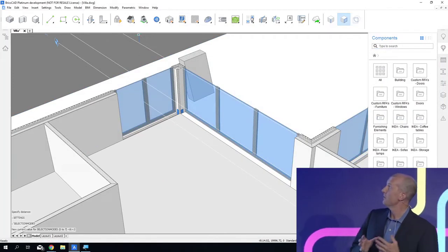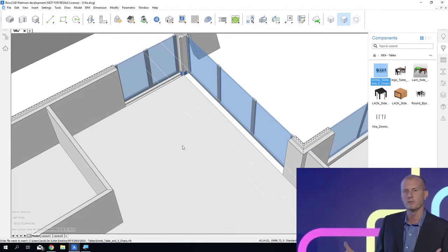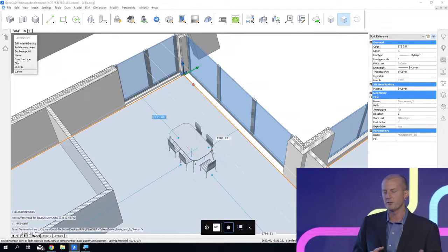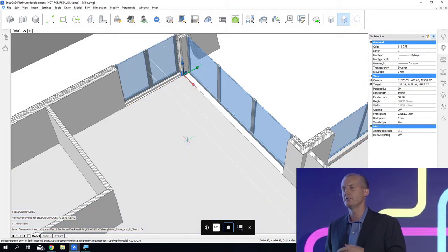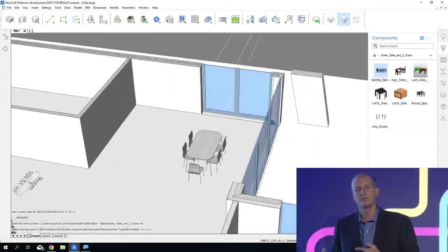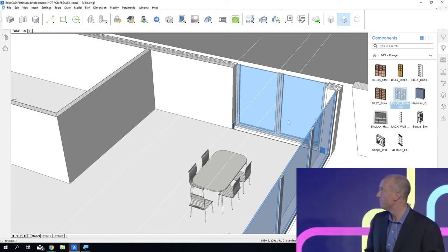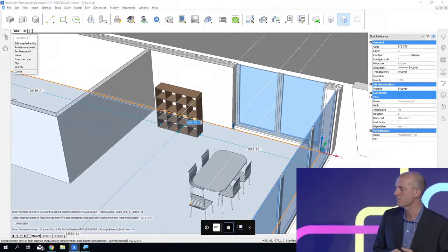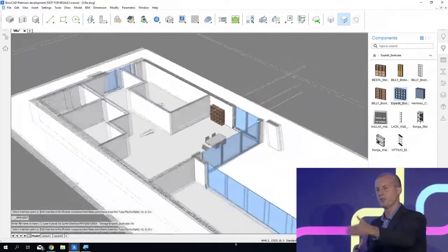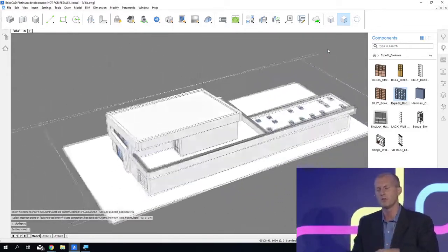And then once we select the folder that those are in, now we've got that as a part of our palette of what we can use for components, and we can drag and drop them into the interior and start to quickly add a bunch of components and start to explore how that influences the interior design of the space. If we want to make some other design changes, we're able to do that. So pretty easily you can see how you can start to build up your design in this way as well, adding detail that comes with the components into the overall BIM.